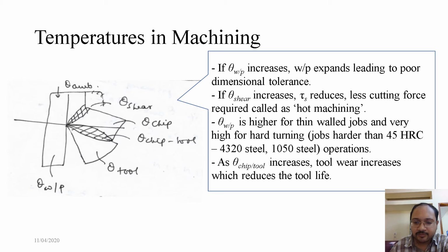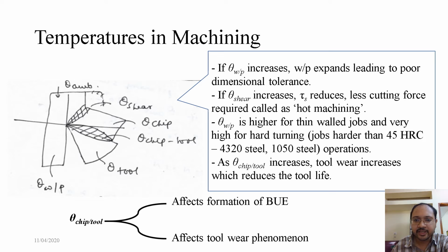As average chip tool interface temperature increases, tool wear also increases, and that finally reduces the tool life. So average chip tool interface temperature affects the formation of built-up edge as well as the tool wear phenomenon.